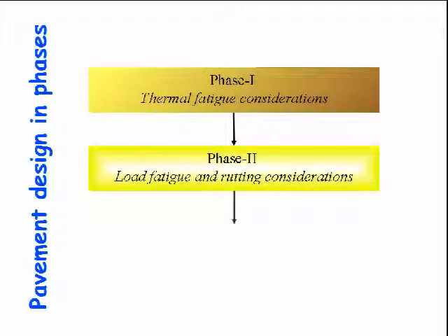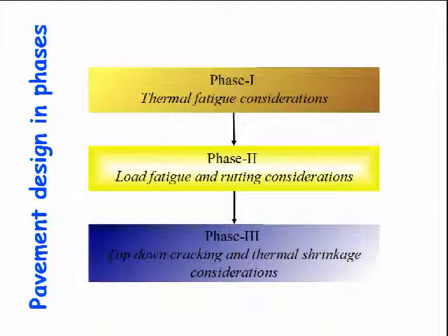And the third phase is the top-down cracking and the thermal shrinkage considerations, which may not be so strongly related to the thickness. So the design approach becomes this: first you are ready with your mix and check whether that mix is good enough to sustain the thermal fatigue or not. Then we use that mix for design of the pavement from the fatigue and rutting considerations. They are obviously related to the thickness.